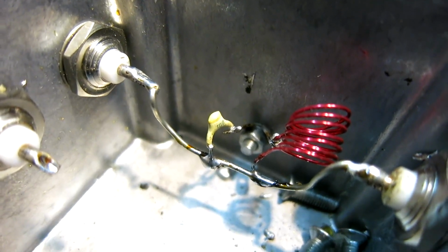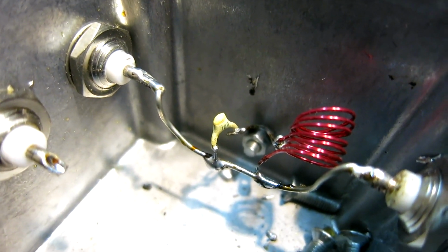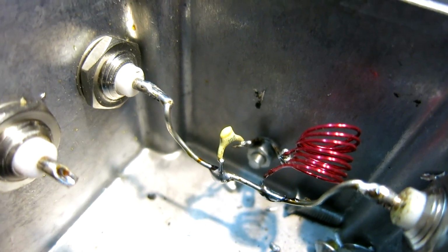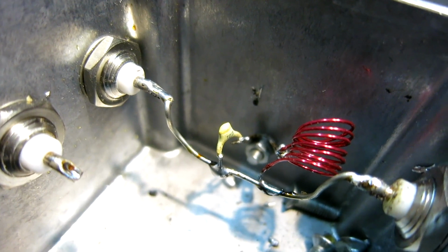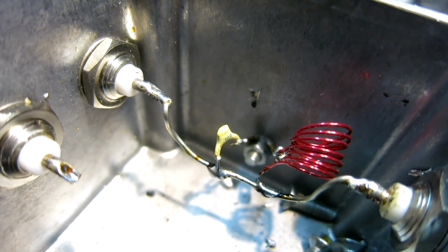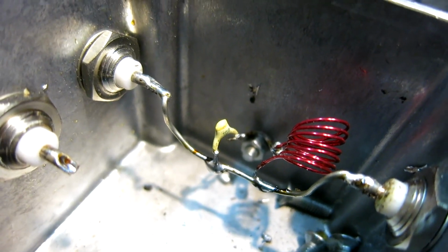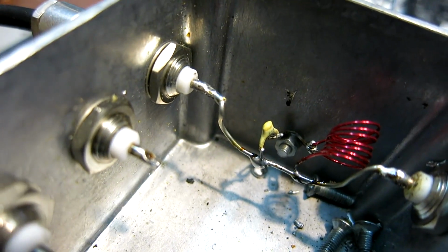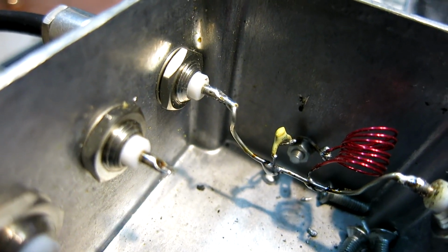In this video I'm looking at the noise, sideband noise added by 1 nanofarad capacitors at 10 megahertz. Here is a ceramic capacitor. I have tuned it in parallel to 10 megahertz to make the transmission from input here to output with low attenuation. It's loaded by the losses of this LC resonant circuit.